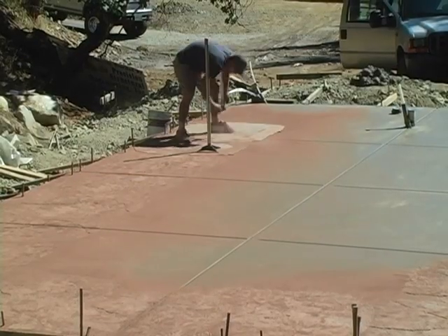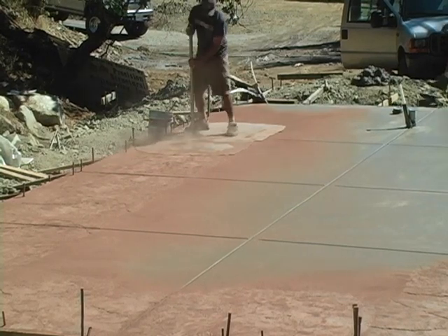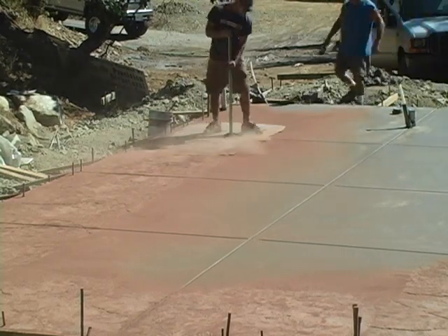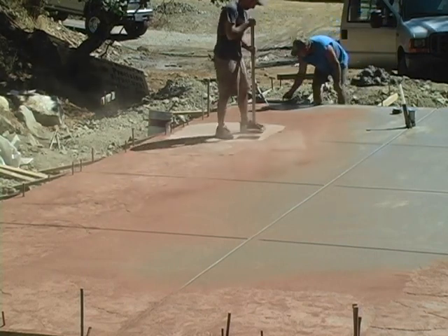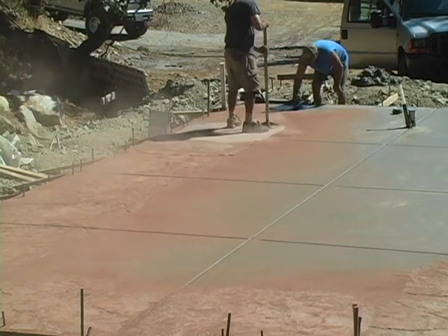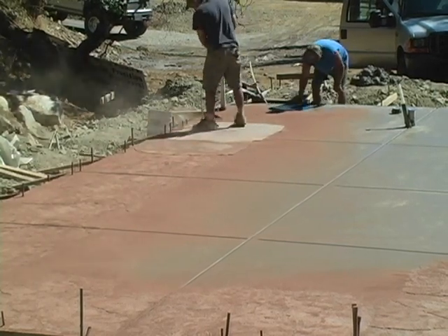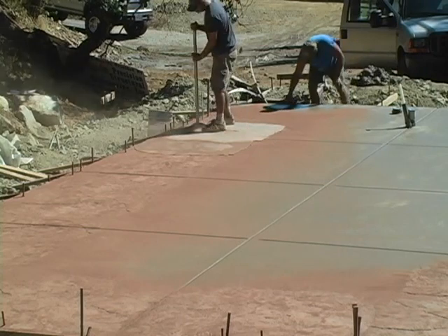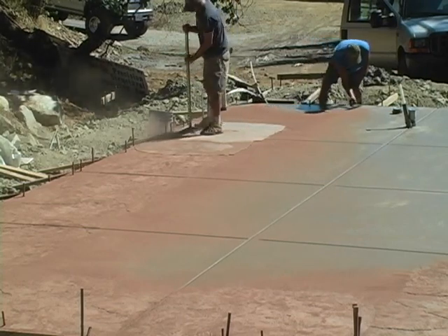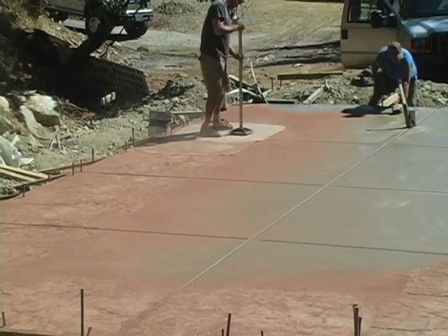So now we'll continue around the outside of the building first. It's important to have a game plan so you don't end up getting stuck somewhere and not being able to get off the building. So here, again, we'll work around the outside first and tamp as we go. Again, just laying enough of the color release ahead of us so that we have something to work on, but not so much that we're putting it out ahead of time where we can't get to it within a reasonable amount of time.